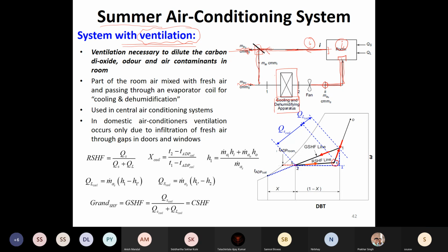And then over here, we have to draw in the same amount of air flow rate which has been exhausted to the outside, so that you still have the mass balanced. So whatever mass is exiting this room is being supplied by the air conditioning system. Okay, so these two get mixed, and then it passes through this cooling and humidification coil, and then it is again supplied back into the room. Okay, so it is like an active infiltration.